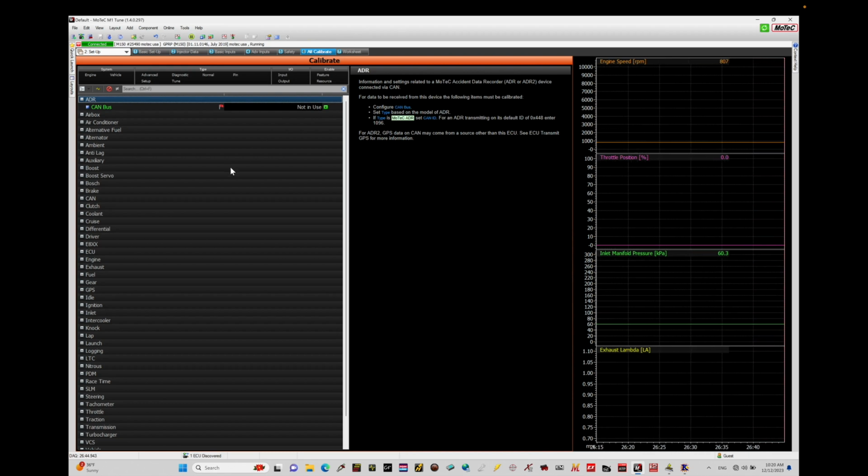Here we're going to jump right in and take a look at programming an output so we can see the various choices that we have within the Motec control strategy, and then we're going to be breaking down what to expect for those output types and when you can expect to use a particular output versus another. So let's move in here and take a look at coolant in our drop down and specifically in our fan. This is going to be using an output from the Motec to turn a fan on or off, or even what's known as a pulse width modulated control. So there's going to be that functionality that we also have to break down here.